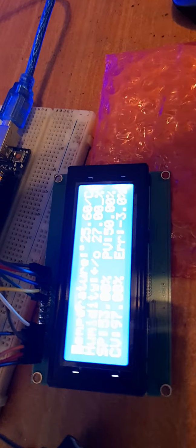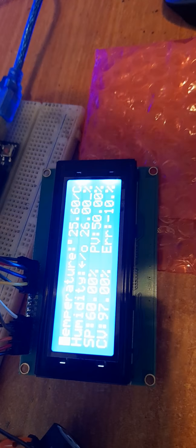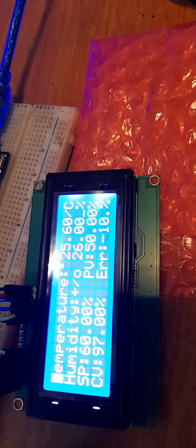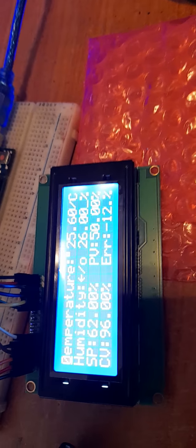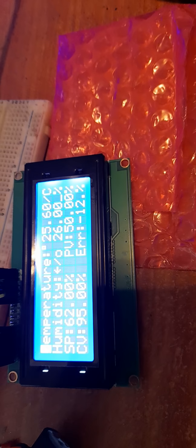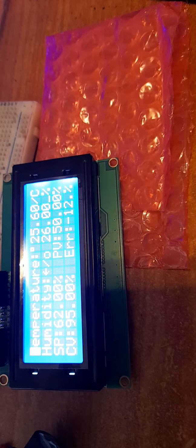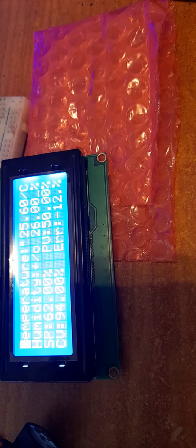The light is killing everything. Let's increase the error. Minus 10, it is going to go faster now. 96%. The CV, our output, the output from the PID, the one I use as my speed reference, is going to be dropping faster. Minus 94, as you can see.